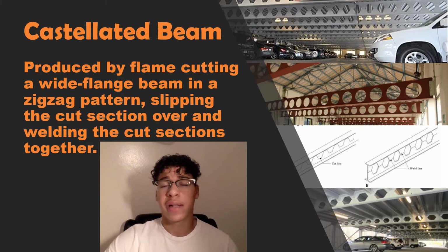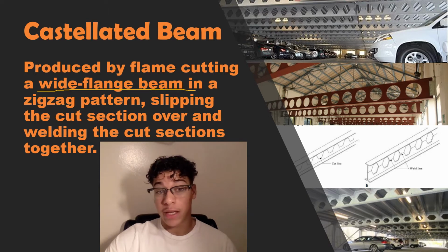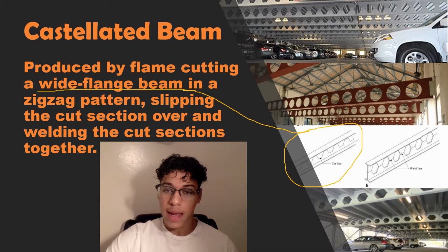So here we have the castellated beams, which are produced by flame cutting a wide flange beam in a zigzag pattern, slipping the cut section over and welding the cut sections together. So those are basically three steps, and let me just show you those three steps. The wide flange beam is illustrated by this image over here, and the cut sections are these zigzag patterns that we see all over the beam.